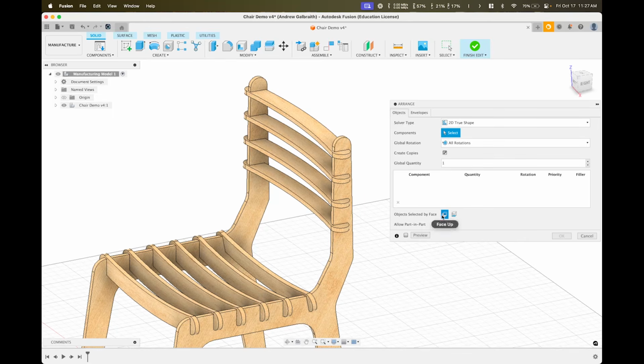what orientation you're selecting things in. Because if you had a half depth cut, but then you selected that side to be down, the CNC can't cut up from underneath. It can only cut from the top. So keep that in mind when you're selecting things.